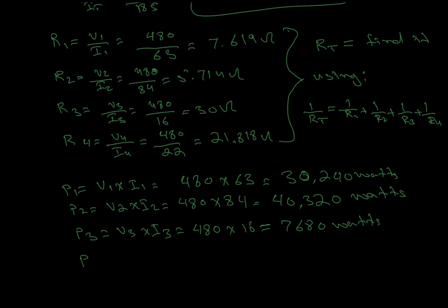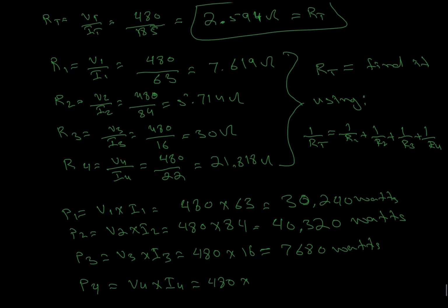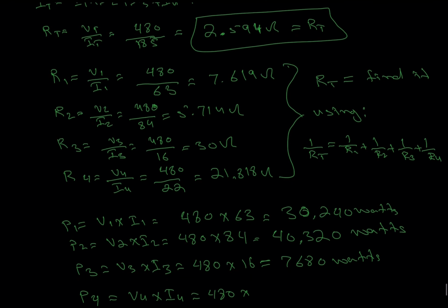And P4 will be equal to V4 times I4. That will be equal to 480 volts times 22 amp, and that will give me 10,560 watts.